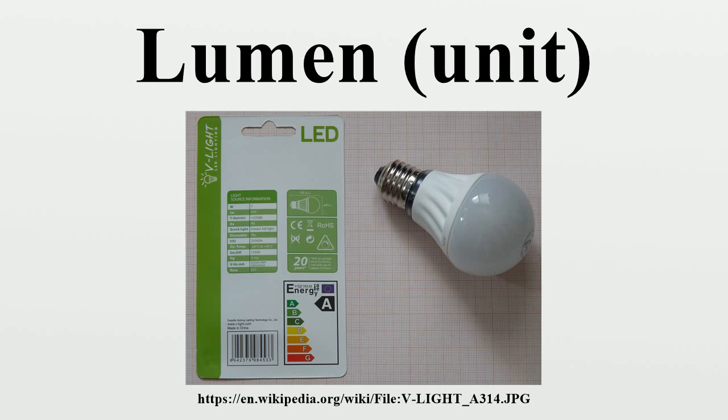Lighting. Lamps used for lighting are commonly labeled with their light output in lumens. In many jurisdictions this is required by law. A 23W compact fluorescent lamp emits about 1500 to 1600 lumens. Many compact fluorescent lamps and other alternative light sources are labeled as being equivalent to an incandescent bulb with a specific wattage. Below is a table that shows typical luminous flux for common incandescent bulbs and their equivalents.